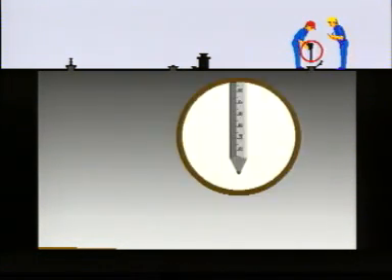Disputes on ROB are very common. You should never allow the loading arms to be disconnected until you know that there are no such claims. You should always be prepared to start the pumps of the vessel in order to show that disputed volumes are unpumpable or out of reach of the cargo pumps.